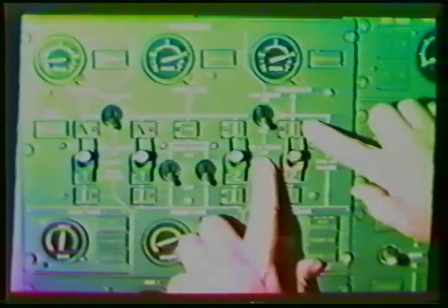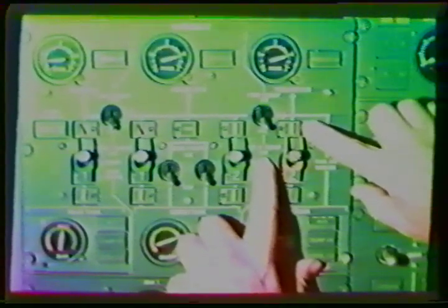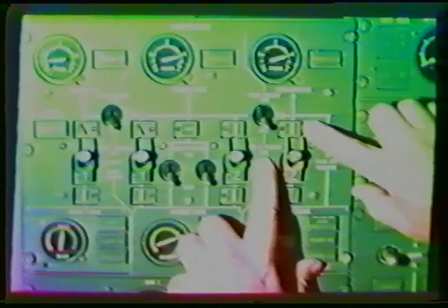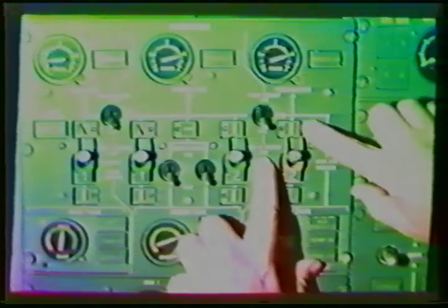The normal position for a pump selector is on. The associated engine pump magnetic indicator, or MI, which monitors the pump's outlet pressure, will be amber until the engine is rotating, at which time the MI will go in line, signifying that the related pump is now producing pressure. Here, the number 2 engine has been started. Consequently, the green and yellow systems are being pressurized.